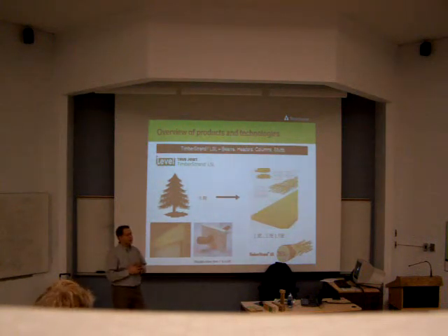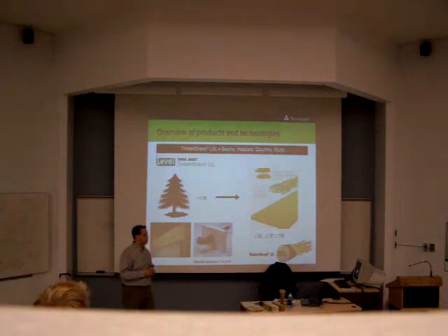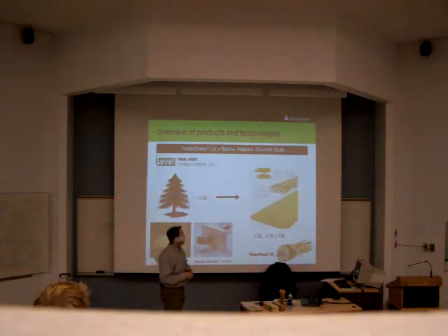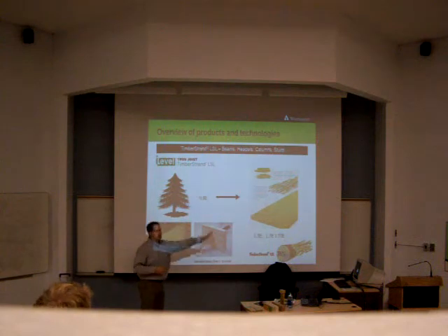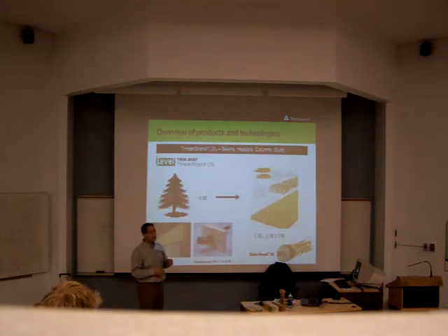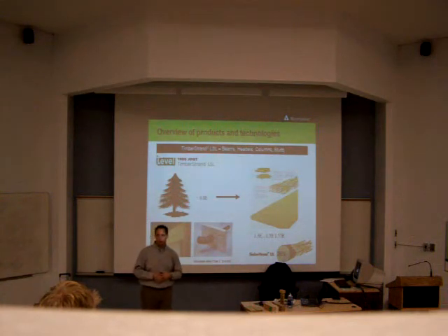There are many design properties to a piece of wood in general, or a piece of steel, or concrete, or what have you. One of the most notable ones is what we call E-value, or modulus of elasticity is what it stands for. Basically, it's how much does it bend, or what's its resistance or strength in bending. So the higher the E-value, the stiffer that piece of wood will be.